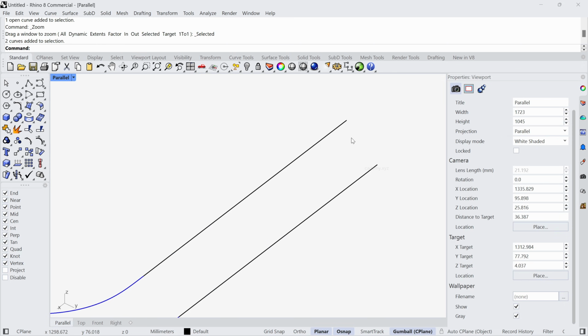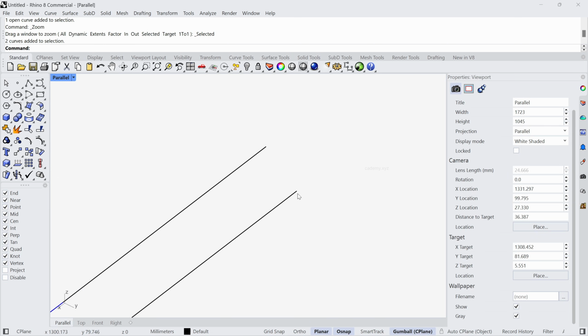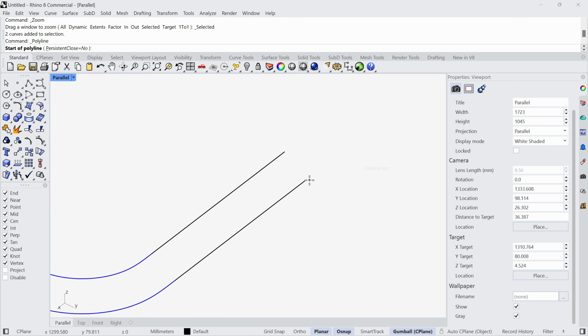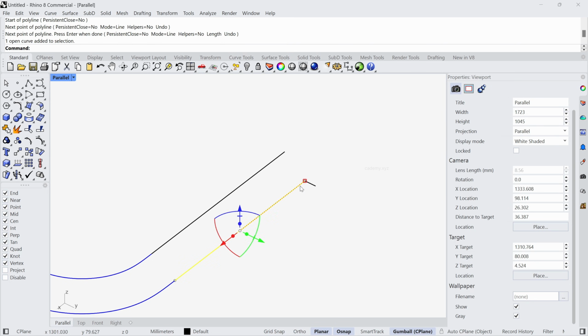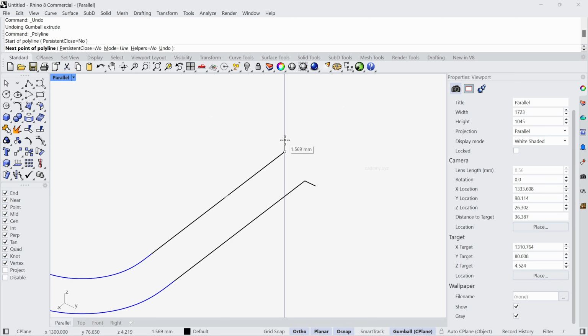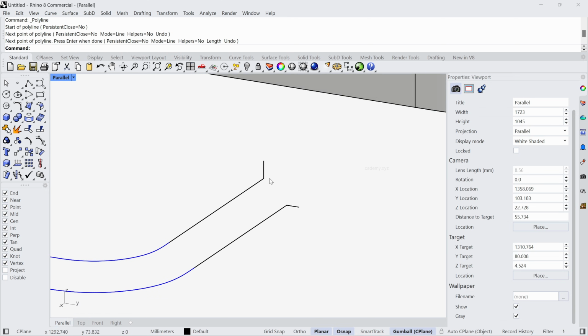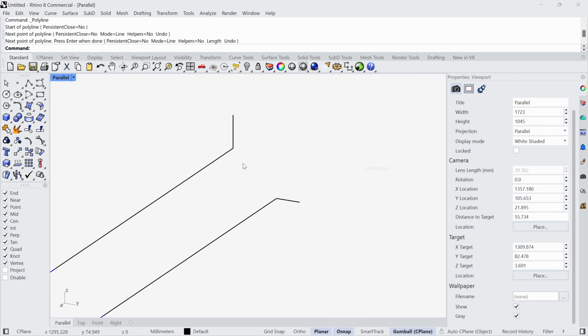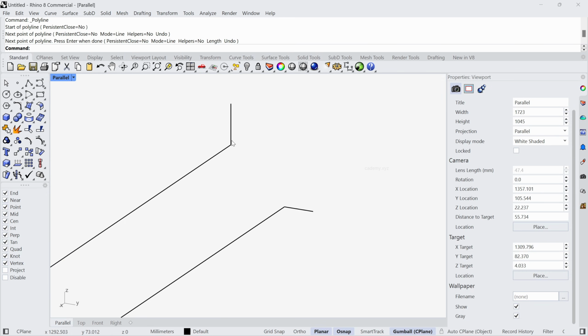Now let's create the blend between these two curves. Now I want to maintain position, tangency, and curvature continuity with the bottom surface. Okay, and on the top side we need position, but let me also add a line in the z-axis so that we can blend between these two curves. So here we need position, but let's see if we can get a better result by making a tangentially continuous curve between these two curves.